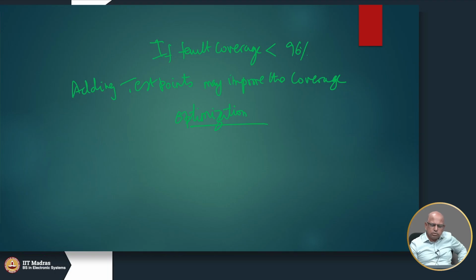It is not easy to find a good algorithm to solve this optimization problem. You have to use some sort of heuristics. So, one heuristic could be run the SCOAP algorithm and find where the observabilities are very high, and start one by one. First select one test point and see how much it improves, and then try another one. You could try that kind of approach.